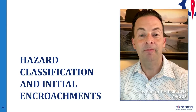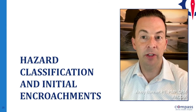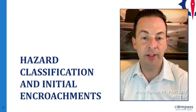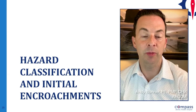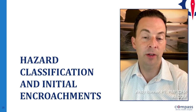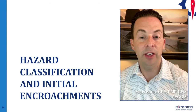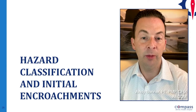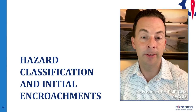Great, thanks Isaac. So the next set of 2D floodway exploration and testing that we wanted to share with you is related to leveraging hazard data, or depth and velocity data, to help inform initial encroachment placement. The question we wanted to ask ourselves and try to answer was whether we could use that hazard data to help reduce the number of iterations necessary to land on a floodway delineation that would comply with regulatory surcharge limits.